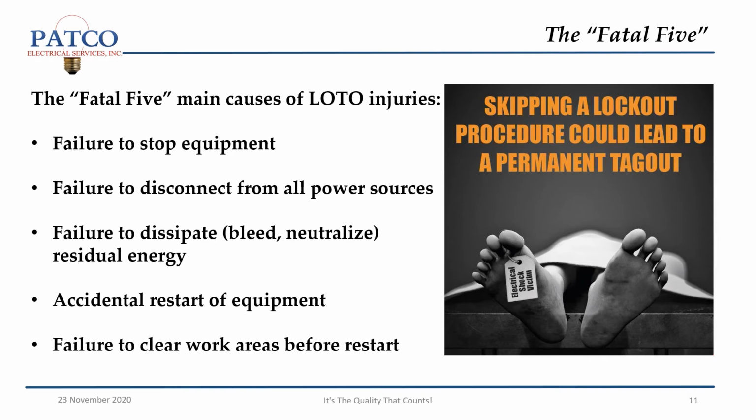The Fatal 5. The Fatal 5 is the main cause of LOTO injuries. It's failure to stop the equipment, failure to disconnect from all power sources, failure to dissipate, bleed, or neutralize residual energy, accidental restart of the equipment, and failure to clear the work area before restart.